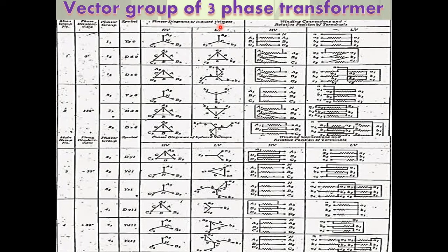Its salient aspects: first, it is economical for small HV transformers. Second, it is possible to provide neutral connections. Third, no triplen currents flow, neutral voltage may oscillate, and triplen voltage may be high in shell type units. Third harmonic currents and voltages circulate in the delta.